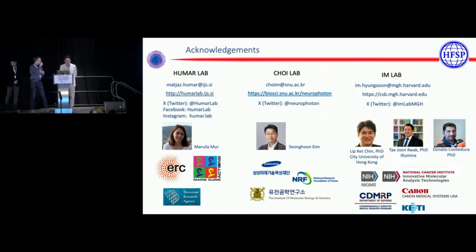If I may add one more thing, one of the advantages of using the laser is that it has a really sharp peak compared to a fluorescent signal. And then you can excite or emit the laser at different wavelengths. So in terms of multiplexing, you can achieve a much larger, broader, higher number of multiplexed channels compared to conventional fluorescence. So that's another advantage of using a laser, in addition to the really high power light emission.